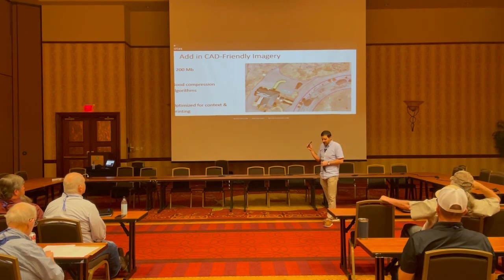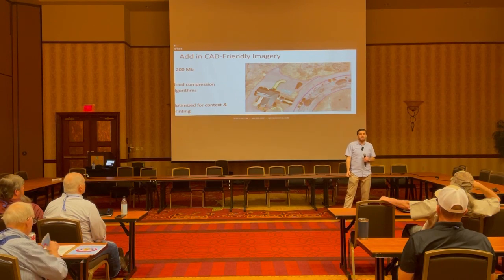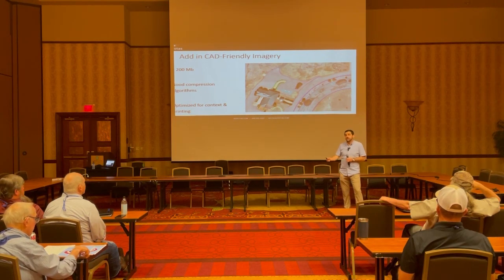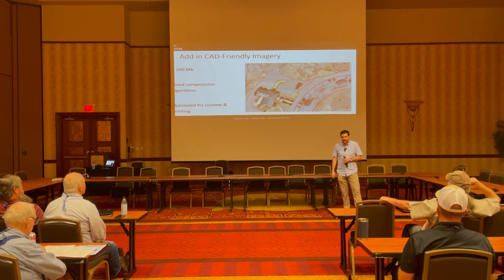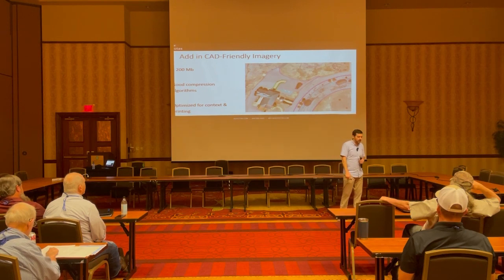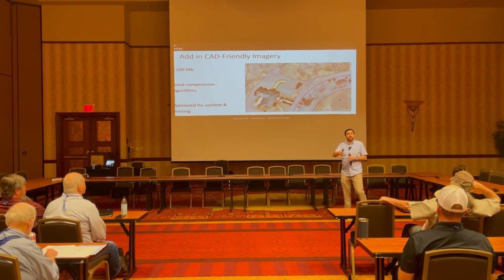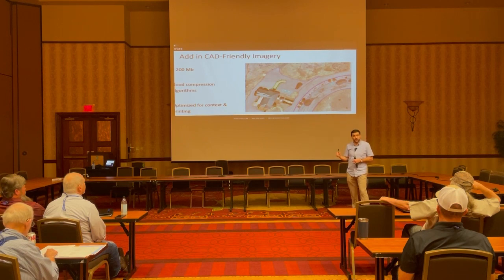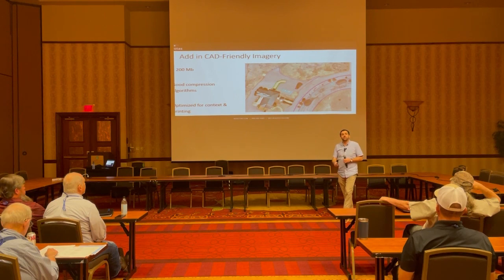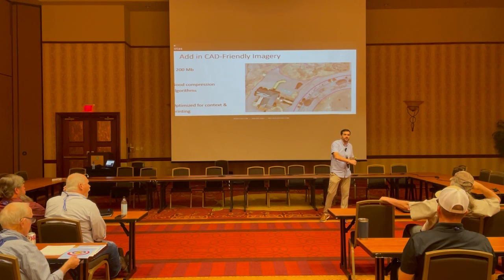I'll take an extra minute on this because it's another tricky one. If you've processed drone data, you know the full resolution orthophoto is massive and usually can't be imported into CAD whatsoever. You could just aggressively downsample it, and you're losing a lot of this good data that you've gotten before. Well, my advice, first of all, you should never extract your data from a program like Civil 3D because it can't handle the full resolution imagery. You always want to do your drafting, to draw those lines, in software that can use full resolution imagery.